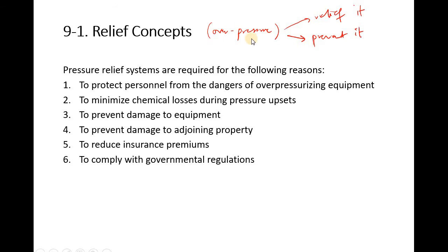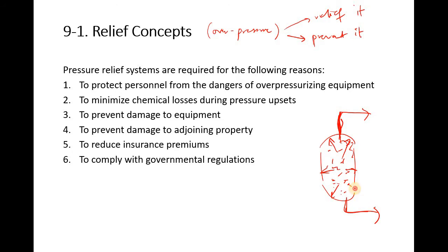Why? Because if this overpressure happens, it's collecting up here, and what happens? It's not enough for the gases to pass through, so it still collects and presses so hard that the integrity of the vessel we have here cannot withstand that pressure, and then it blows out.